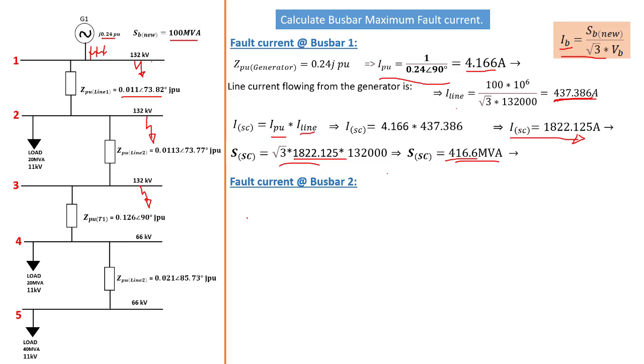Just like we have explained, the generator acts like an internal impedance of a battery. Now to move power from point A to point B, you need to ensure that between A and B you have minimum resistance, so that your maximum power on the input will be maximum power on the output. This basically means we need to add the internal impedance of the generator plus the per unit here of the line, and these together will be the Z per unit total that will determine how much per unit current we're going to get for the system. So let's see how it works.